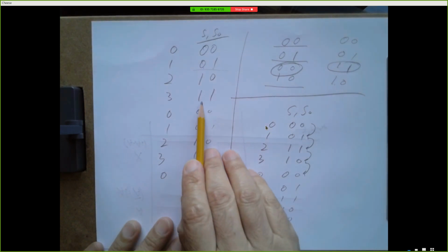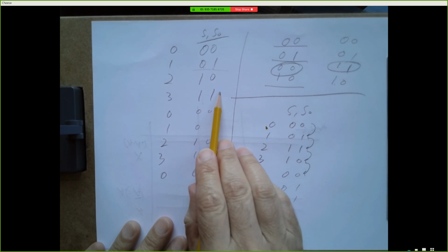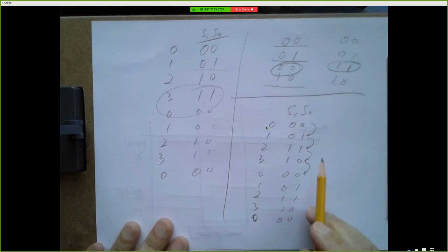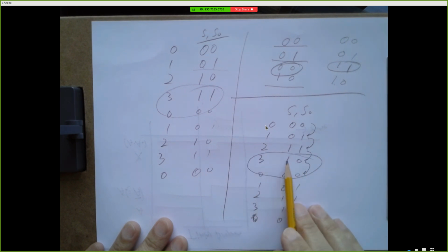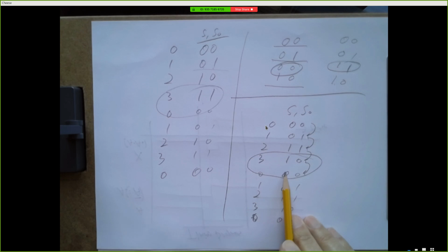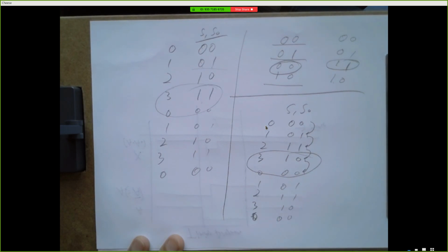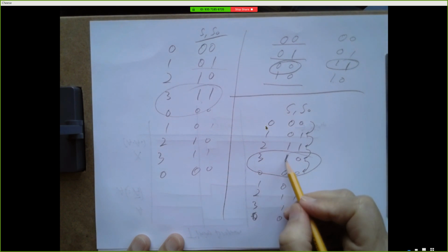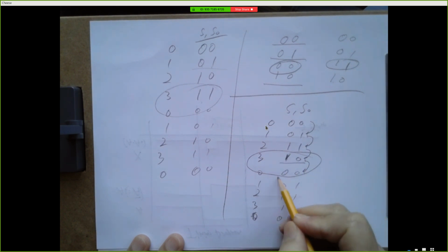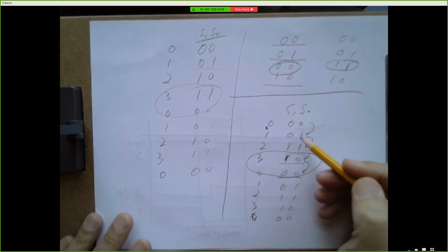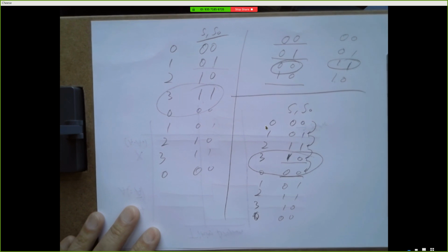And all the way from step 3 to step 0, wow, in our old case, both bits had to change. That could happen in any old crazy order. Here, to change from step 3 to step 0, we just need this most significant bit to change from a 1 to a 0. It might happen in 1 nanosecond, 5 nanoseconds, 7 nanoseconds, but it does not matter. It's going to be in this state for a while, and then it's going to be in that state, with no glitchy intermediate state. So this is a useful order for counting.